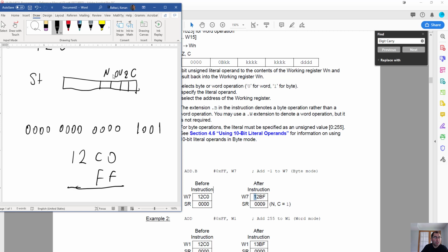You can put the -1, I guess, or do the same thing with FF. So when you add these two, you have F, and what is C plus F? C plus F is B, with carry 1. Because this is a byte operation, this carry is just going to be trashed.